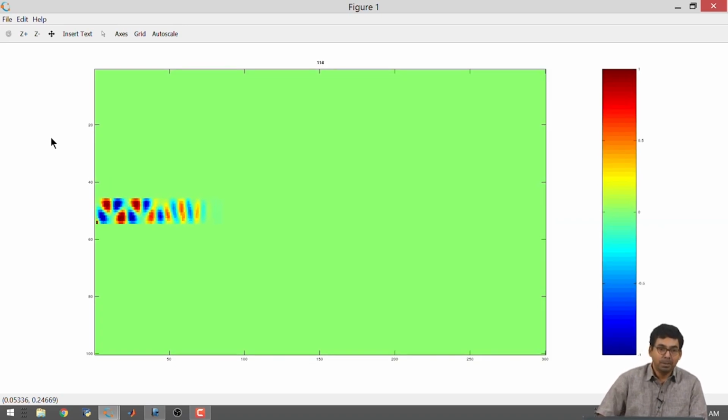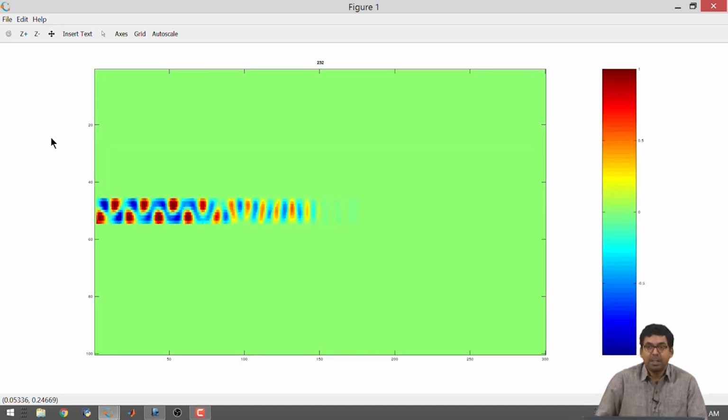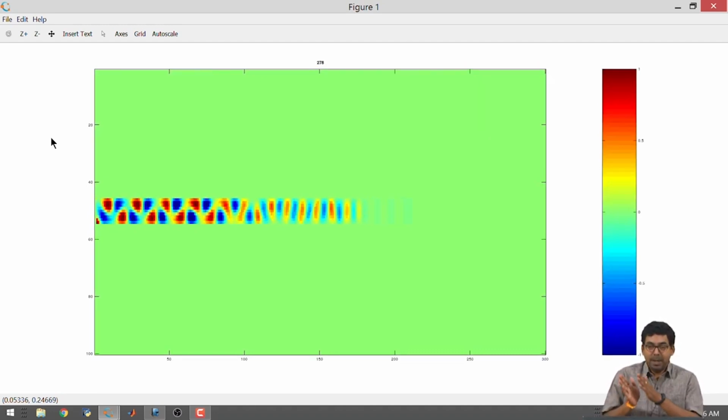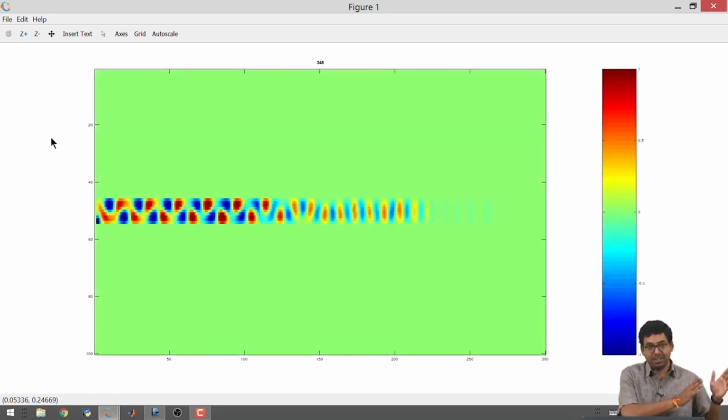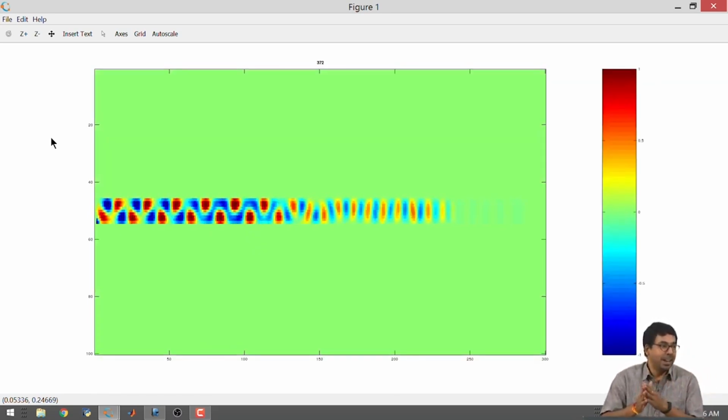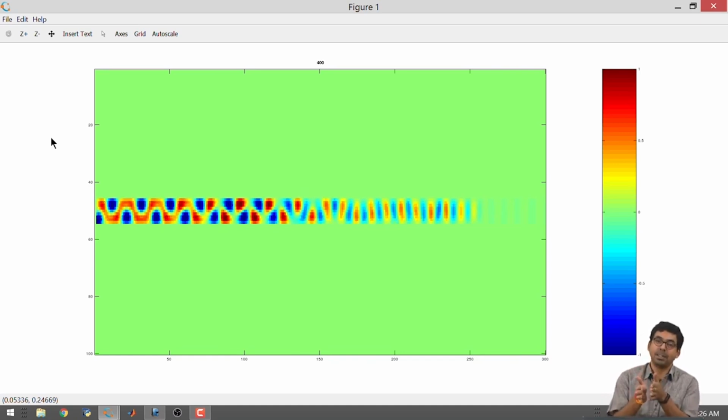Sin n by 2 means that you increase the frequency, but if you increase the frequency of operation, the adjustments you made to the width of the waveguide were valid for the frequency you were using before. Now again, for this operating frequency and this separation, how many modes are supported has to be recalculated.